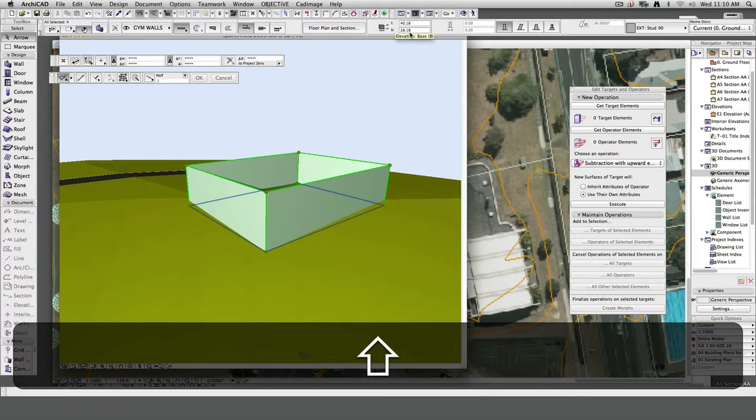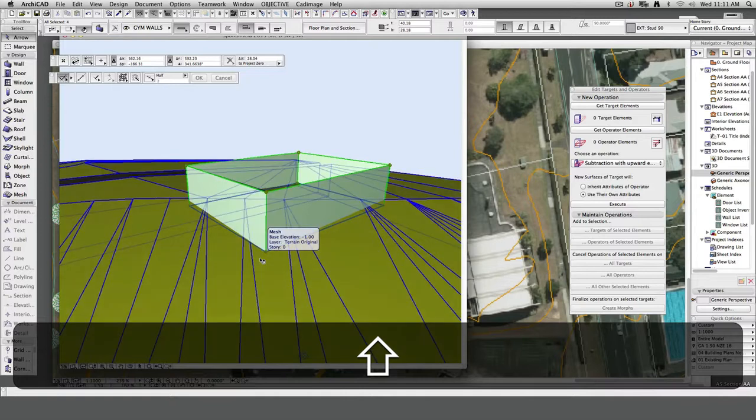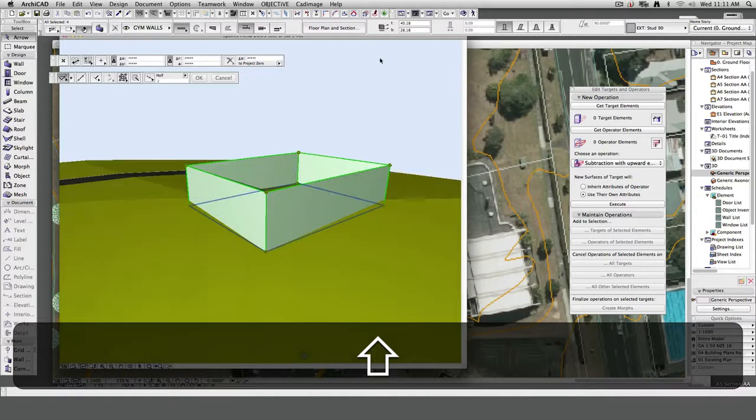Someone said gravity. Correct. I still had the gravity switched on from when I used that column tool, so when I went and drew the walls, I went and set the height. Now that's cool, although then I get funny numbers, so then I go to put my roof in, I've got to put in 40.18 and all this sort of crazy stuff, which I don't really like.